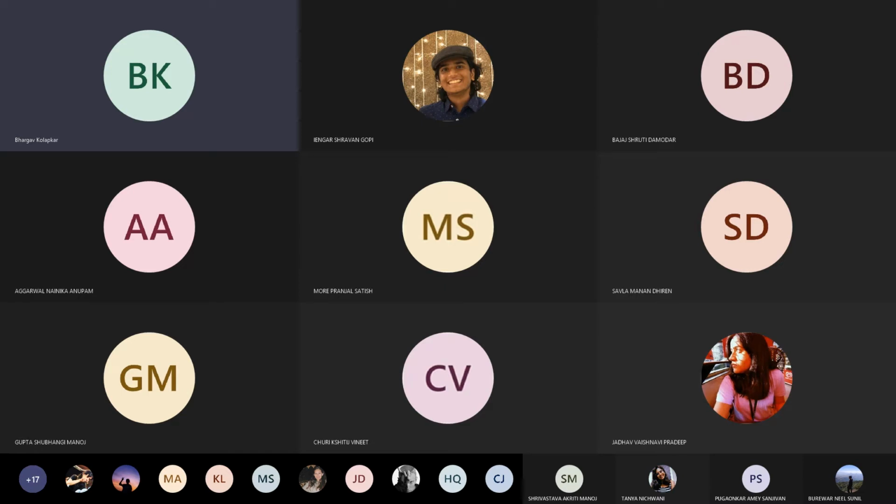Let me repeat it. Depending upon the magnitude and the nature of loads in the column, and depending upon the nature of the soil, there are a number of ways in which we can design and detail this base plate. The easiest one is what is called a slab base. In a slab base, you have a very thick base plate.